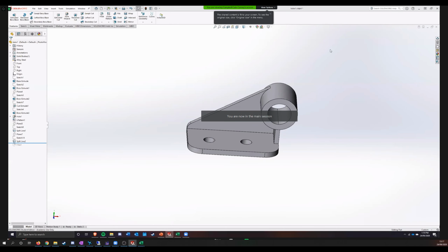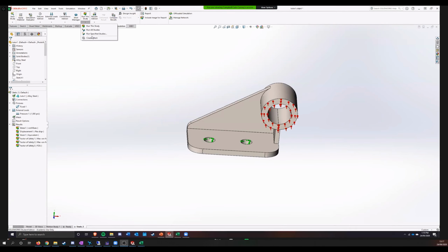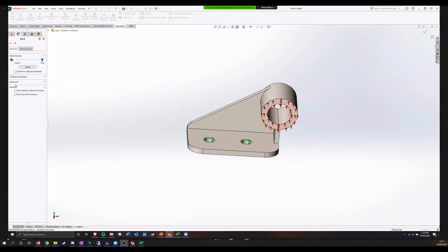Mesh parameters or advanced. When you're creating a mesh, there should be a box that you can check to click draft quality mesh. And draft quality mesh is a TET4. And then it's normally just TET10. Yes, so standard quality mesh is TET10s. All right, so here's